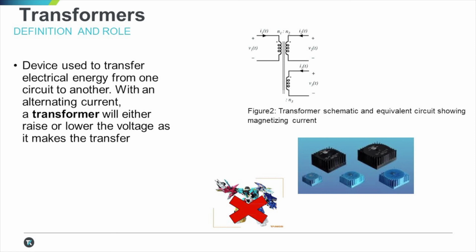The first is isolation, in order to meet safety standards between input and output sides. The other important functional purpose is to step down or step up voltage so that the converters can operate in normal duty cycle ranges. It is worth mentioning that it is possible to obtain multiple outputs through multiple secondary windings, which you see in the upper right-hand portion of this PowerPoint slide. Some of the common converters which use isolation transformers range from flyback to forward, full bridge, push-pull converters, as well as full bridge boost converters and isolated converters.